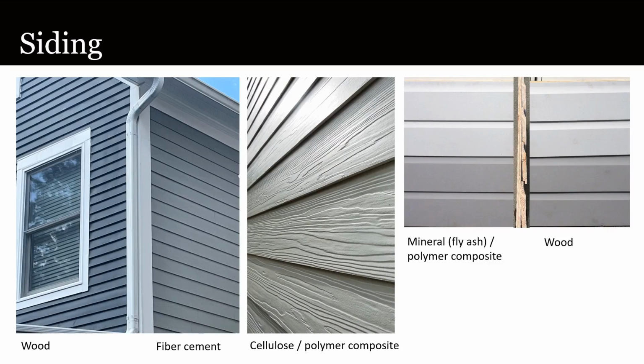Some siding materials have a heavily embossed surface looking like a piece of wood that's been sandblasted, as depicted in the middle photograph. Some materials are available only with a smooth surface, and some offer both options. Since traditional wood was planed, only a smooth option is appropriate for replacing historic wood siding. Though one might create a board and batten siding from materials available as trim boards, the only other historic siding profiles available in a substitute material are beaded edge, that's in fiber cement, or cove or drop siding, available only in mineral polymer composite. None of these materials have the same properties as wood.